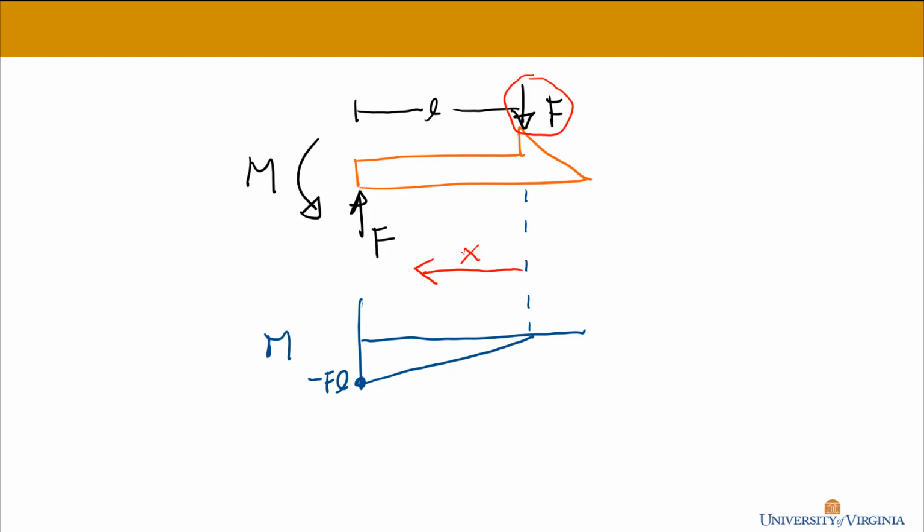And that it's negative on this plot is just a convention. It doesn't matter for the point of understanding whether the part fails or not, and understanding that the maximum moment is experienced at the base where the part is attached to the snap fit.